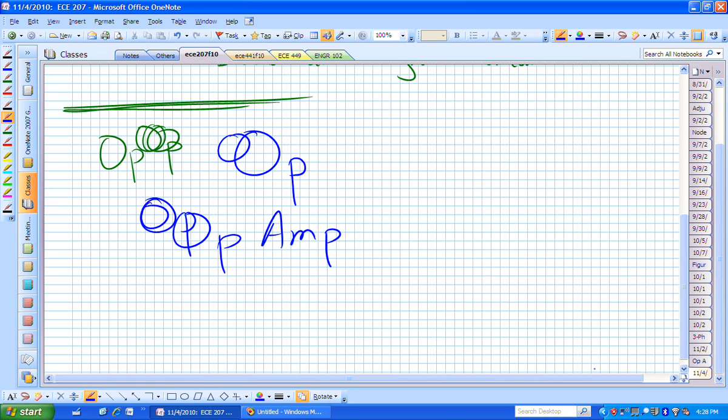Are we okay with that expression? That's just KVL, and it's consistent. We're just living with what we assigned. We assigned some currents, and we're now living under those assignments. Question? V sub I would be equal to the negative of V sub D. Yes, so V sub I is the negative of V sub D, and so what do you think V sub I is? 0. It's 0, based on our summing point constraint. So I just included it so that you knew where we were going.